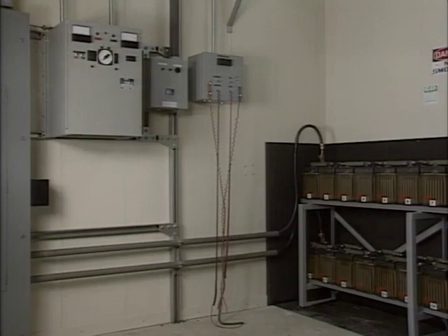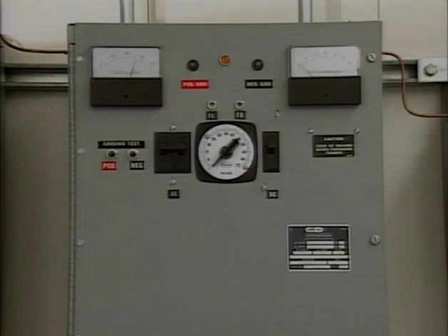As with the freshening charge, float and equalizing charge voltages and times can vary with the type of battery used and with the load limitations of the DC system. Be sure to determine the specific float and equalizing charge voltage and time requirements for your system. Now, in order for a charger to provide the required direct current to the battery and the loads in the DC system, it must be properly maintained.